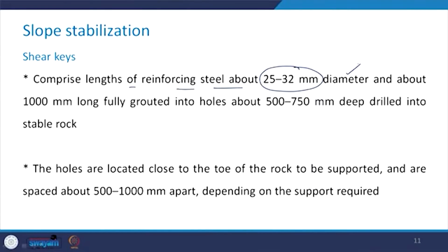These comprise lengths of reinforcing steel about 25 to 32 millimeter diameter and about 1 meter long, fully grouted into holes about 500 to 700 millimeter deep, drilled into the stable rock.